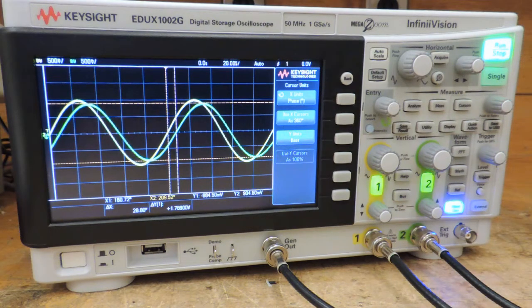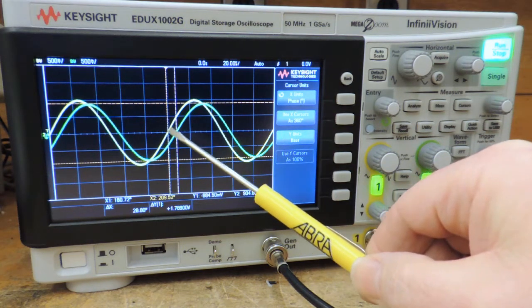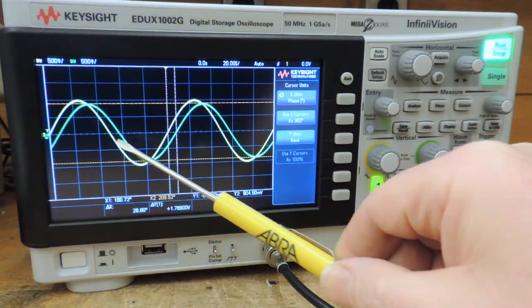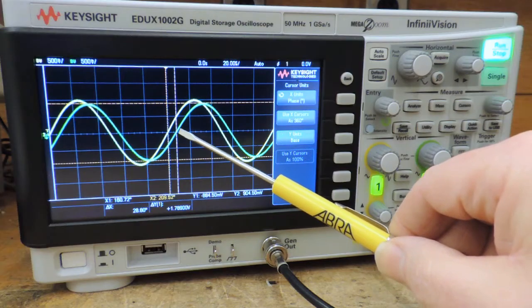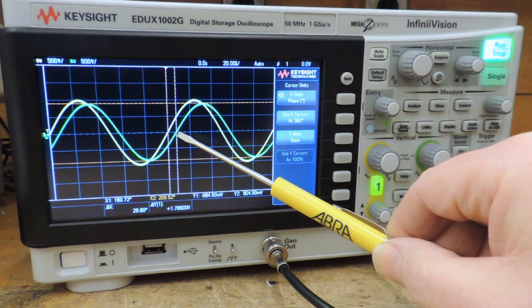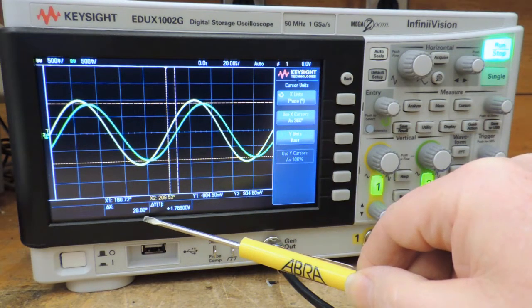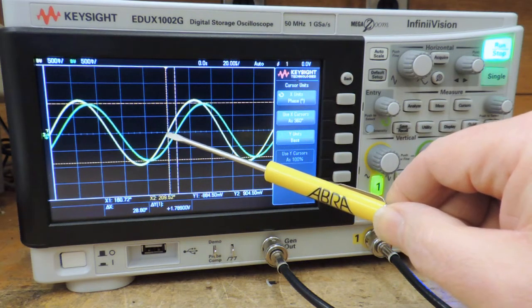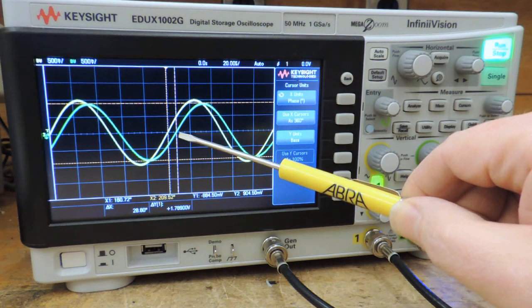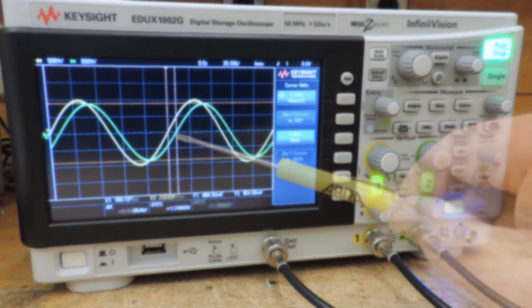So it's very important that when you're doing a phase measurement that both waveforms are either positive going or negative going. Don't try and select a negative going and a positive going. It doesn't work that way. What we want is the time difference between the two waveforms. And here we can see that delta X is 28.8 degrees. So that's the shift between the input signal and the voltage dropped across the capacitor. Remember, this is voltage drop across the capacitor. It's not current through the capacitor.